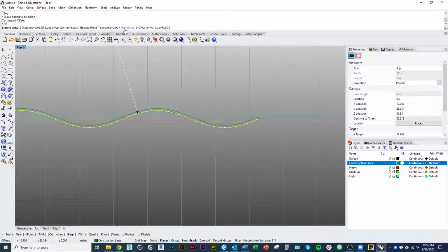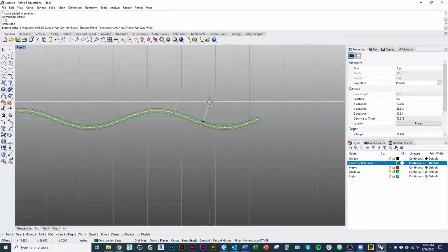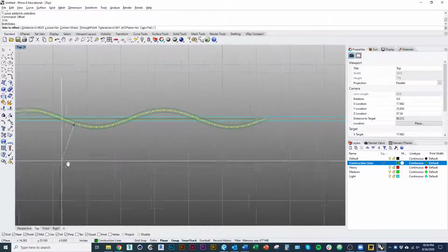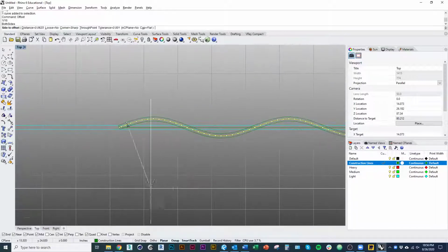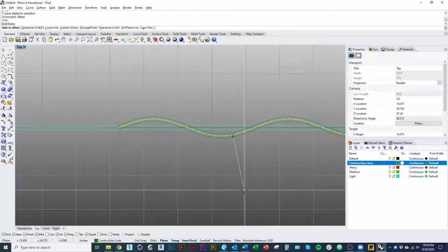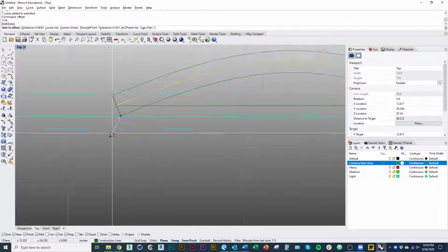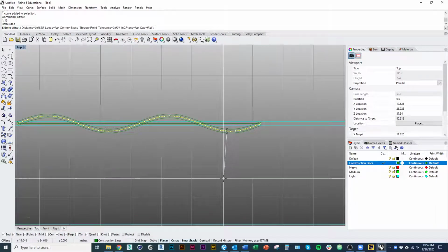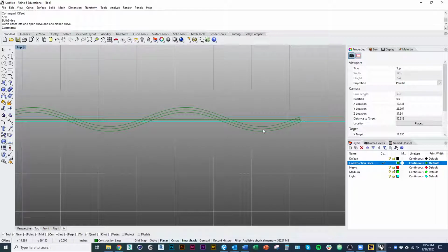The other thing I'll do now is use the option Both Sides. See, that'll offset it in either direction from the center line, and that'll enable me to offset it to the top and bottom to get that thickness total. And you can see at the ends, it's kind of going within the thickness of my handle. So I'll click right there. And so now we have that thickness.